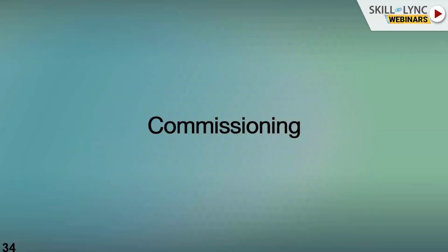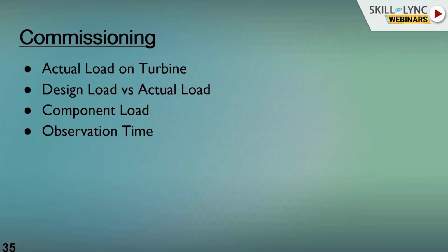And commissioning. In commissioning, normally they verify the loads: the designer gave the initial load, and based on this they calculate whether the turbine withstands the particular load, the design load versus the actual load. As I told earlier, the power curve: the designer initially releases the theoretical power curve. After installing at the site, they go for an actual power curve.